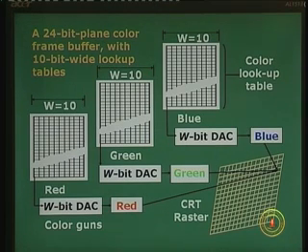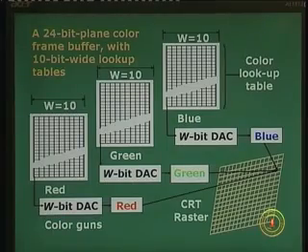Okay. So, we stopped in the previous slide with the lookup tables. Now, the lookup table contents, which are addressed by the corresponding register, 1 out of the 2 to the power n or 256 positions, one such content will be dragged out like a memory address, and then memory contents are taken out and passed on to a W bit wide DAC. Okay. W bit wide digital to analog converter, 3 DACs again for 3 separate colors R, G and B, or red, green and blue, and the DAC contents are again output to the corresponding red, green, blue colors, and they all converge to a single pixel, a triangular phosphor dot arrangement for RGB in a single raster plane. Okay. So, I hope this arrangement is getting clear.